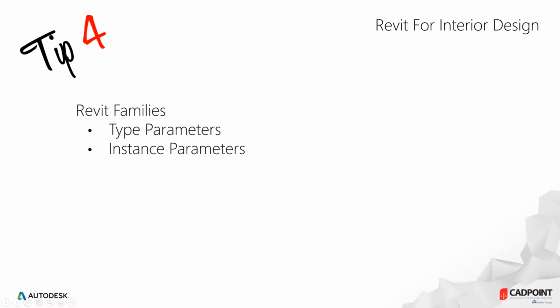It's integral for you to know the terminology here. So let's use a chair as an example. If we create a chair from scratch, we call this our family. When we save it, it creates a family file. Now, rather than having to make two different families to create a chair with arms or not, as we just saw, we can add a parameter into the family, and we can turn those arms on and off.